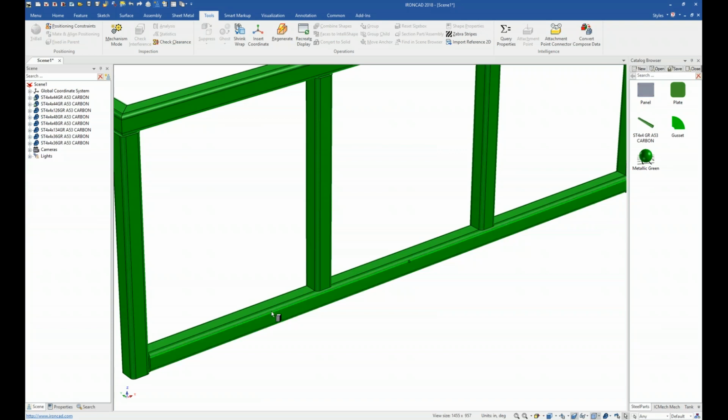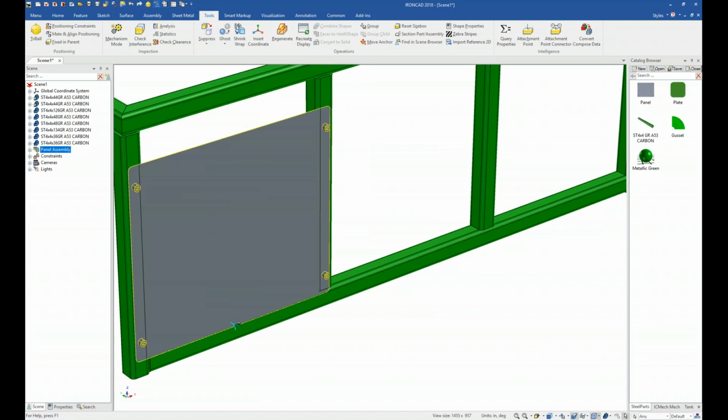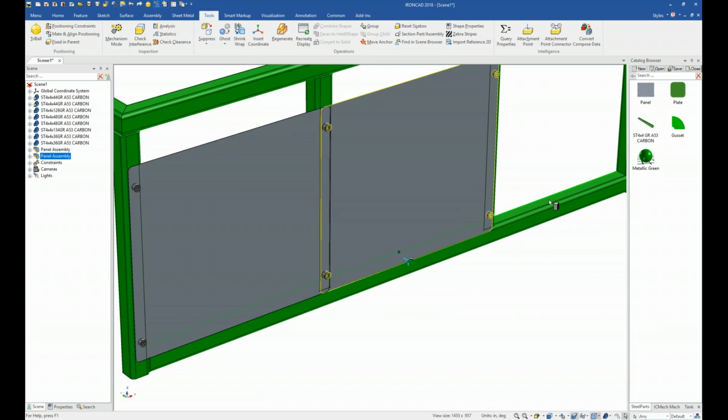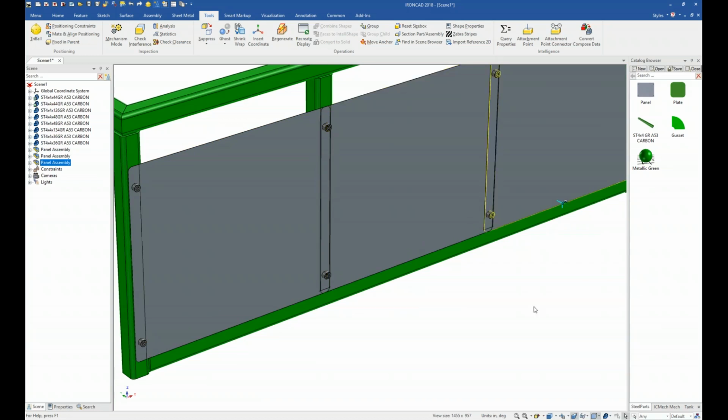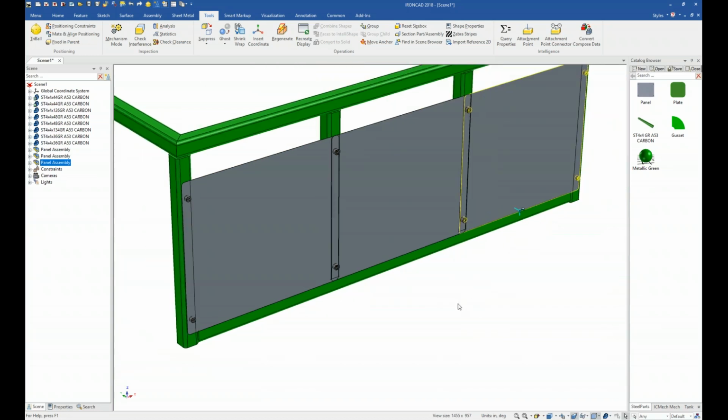So when I drag and drop this out onto this part, all I need to do is be near one of those attachment points, and notice it'll position itself, orient it, and align it. And how it does that is based off these anchor points. So it anti-aligns the Z-axis you see here, the long one, and aligns the x-axis. So if we continue to drop these out here, I can drop another one here and another one there. It finds those nearest attachment points and drops those panels for us.